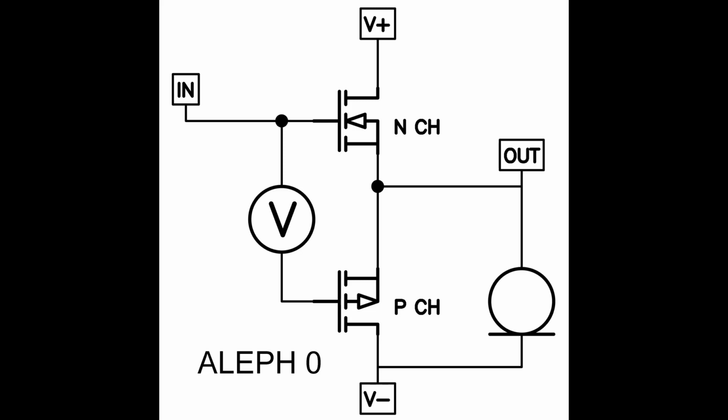This DC current source created the asymmetry which gave me the harmonic pattern where the amplitudes declined dramatically with the order, so that third was much less than second, fourth was much lower than third, and so on. A much desired trait that works very well, and I've used this and similar techniques in many power amplifiers. However, as far as I know, I'm the only one doing it, which is fine by me.